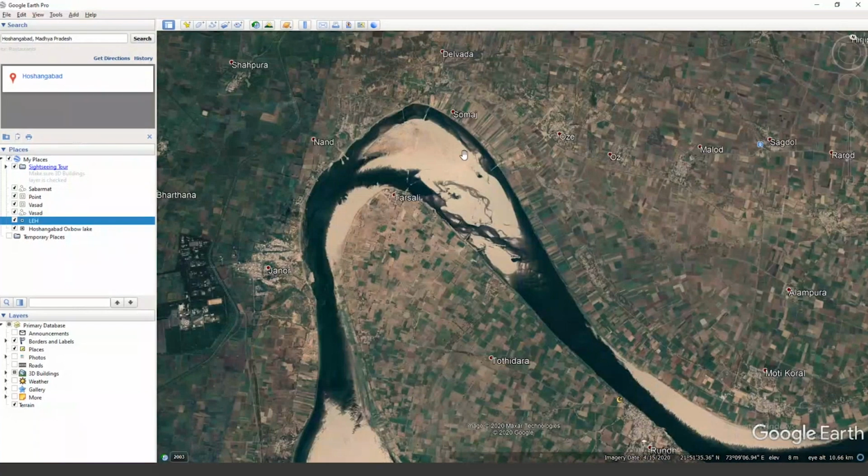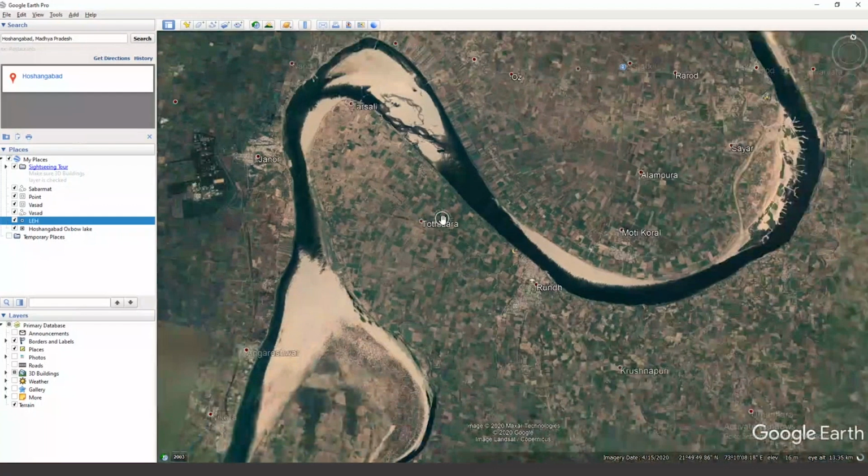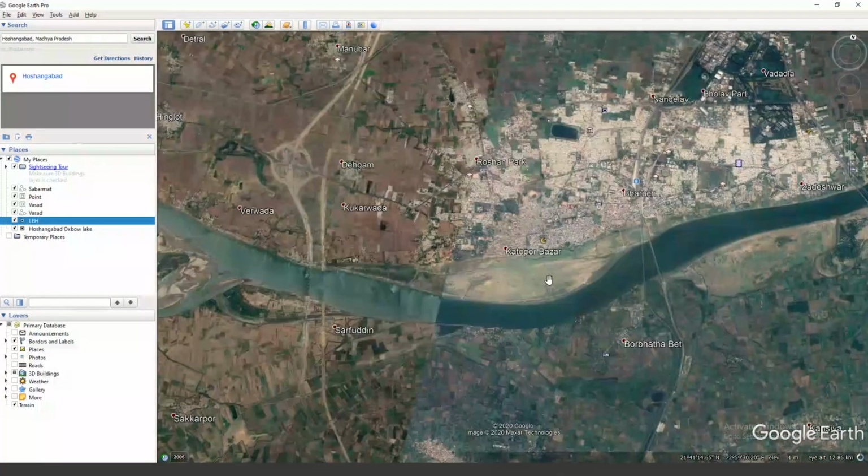As a result, the river will start depositing on these bends. The deposit on the inner portion of the curve, we call a point bar. If these deposits form along the sides of the river in a straight line, we call them lateral bars. Sometimes the lateral bars have an alignment perpendicular to the direction of the flow, which we call transverse bars, and there are longitudinal bars, something like that.